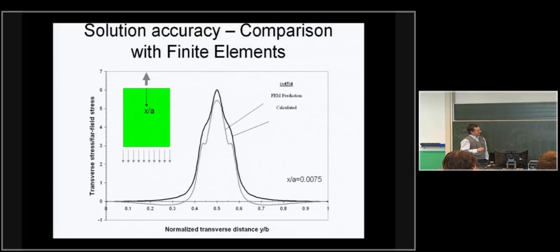Again, the sigma y stress is very close to 0 if y over b is less than 0.2 or so, or greater than 0.8. So there's again a region in the center of the plate which would require reinforcement to cover sigma y. Now you can see also at the same time that sigma y and tau xy do not necessarily correspond to the same region in the center in which they are appreciable. One was, tau xy was from 0.3 to about 0.6 or 0.7, while the sigma y is over a slightly larger region.